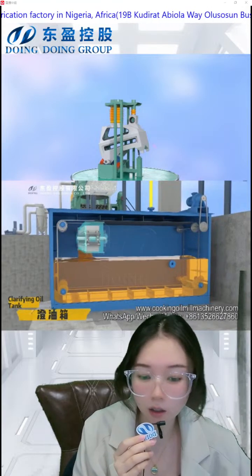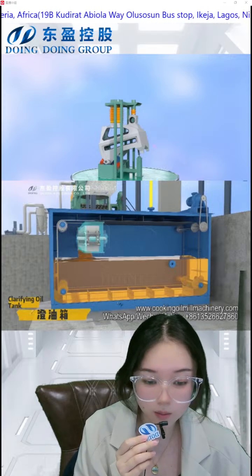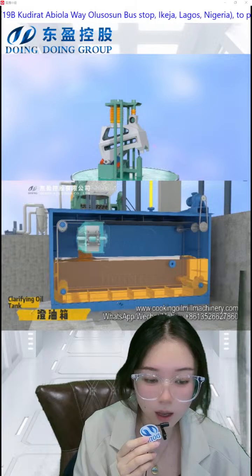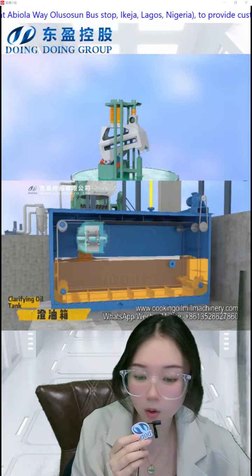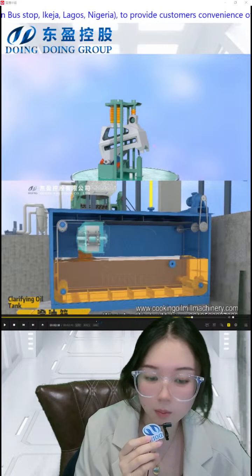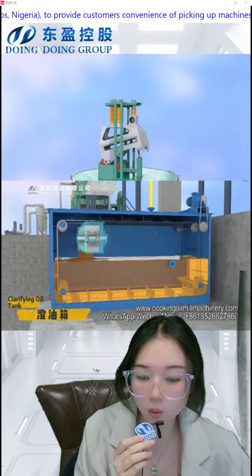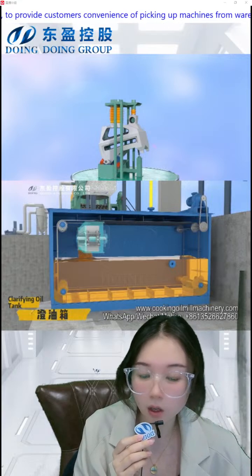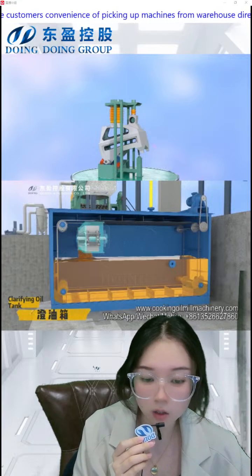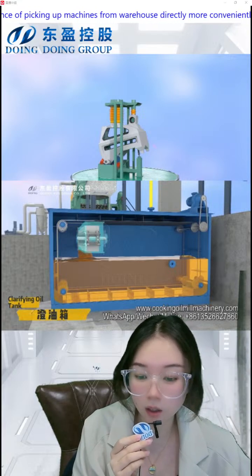The clarifying oil tank can serve as temporary storage, control the production rate, and improve production efficiency. On the other hand, by standing still, the oil residue will settle to the bottom of the tank due to gravity, making the crude oil cleaner.